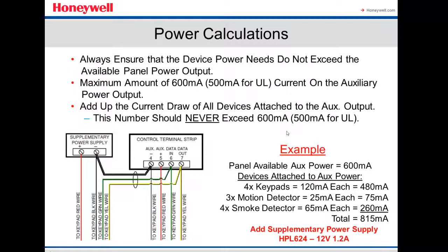Here's an example: if you have 4 keypads, each one using 120 milliamperes, it goes up to 480 milliamperes just using the keypads.